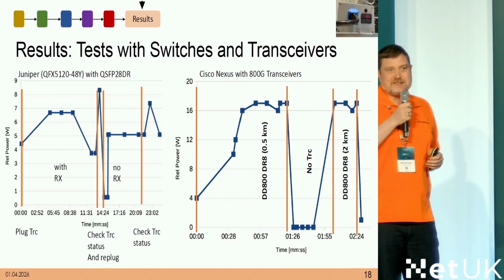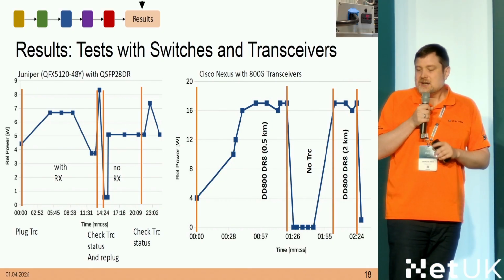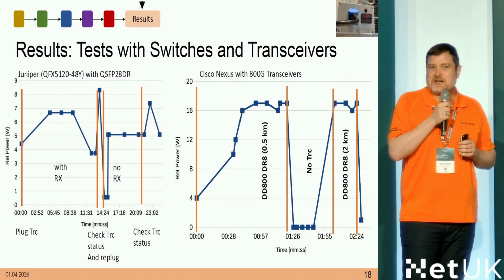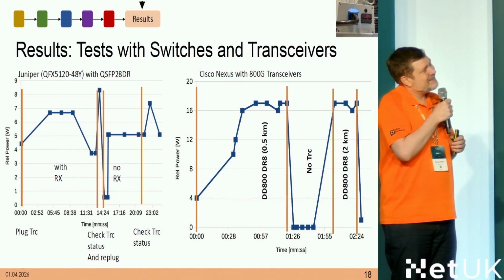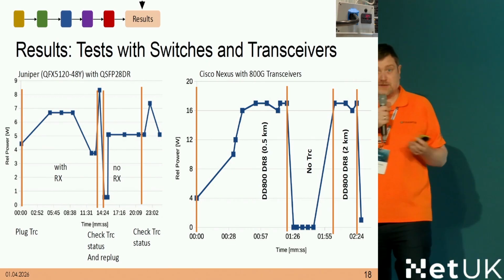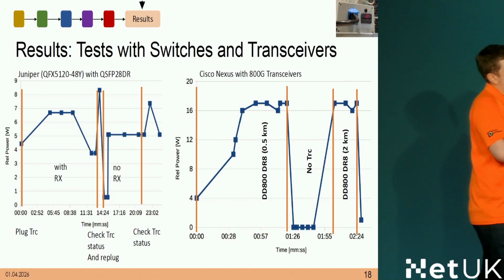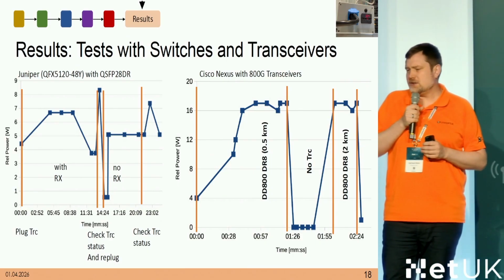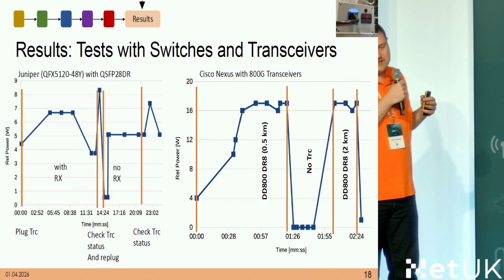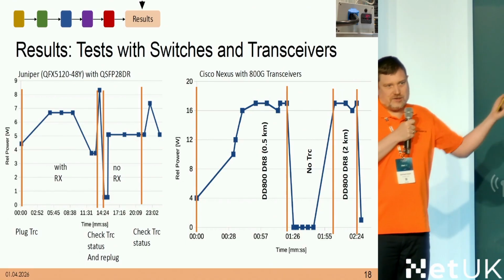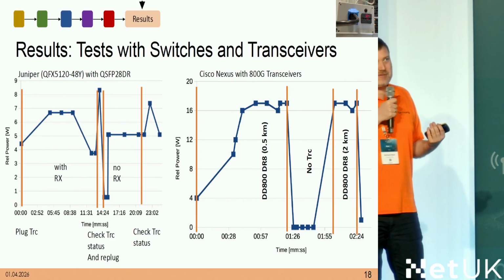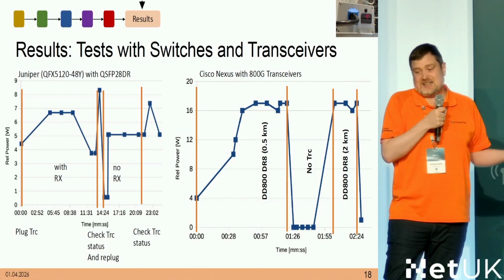Now, what happens if I disconnect this jumper cable? That is what I did. With the jumper cable not connected, you can see that it still is consuming 5 watts of power. And that is the thing where I think we should improve our operating system on the switches. So please ask your manufacturers to also look into this. If you have a lot of unused ports, you should be able to shut down your transceiver and not consume that power. Because you can turn on a transceiver, you are not transferring any data, but the laser is turned on, and this is quite unnecessary.